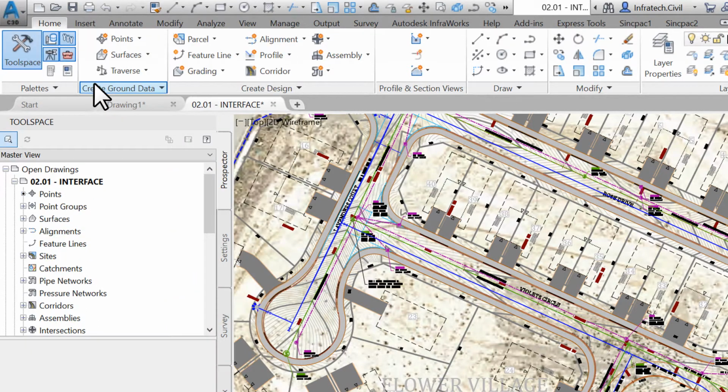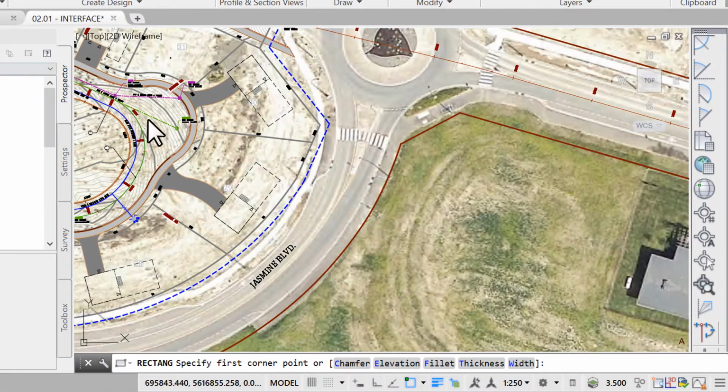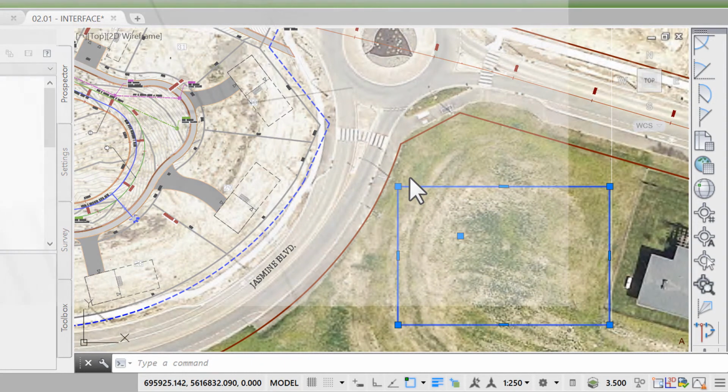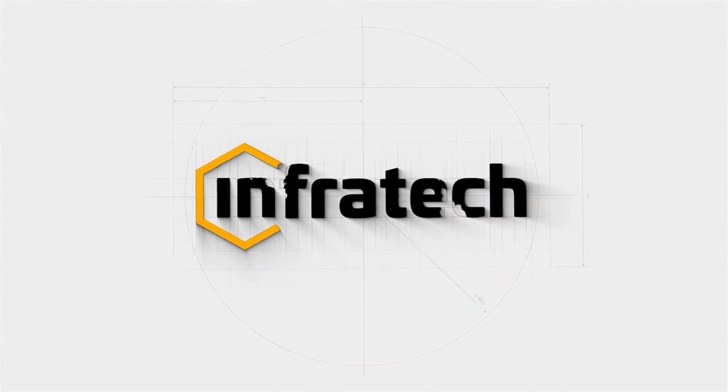If we click on it, we can come to the drawing area and simply click the start and end point and draw a rectangle. So these are actual commands we can run, not just an information help menu. The Search Commands box is very useful when we are looking around for commands that we don't know or don't recall. Select the polyline that we have just created and erase it using Delete from your keyboard. That concludes the section on the application menu. Next up, the ribbon.